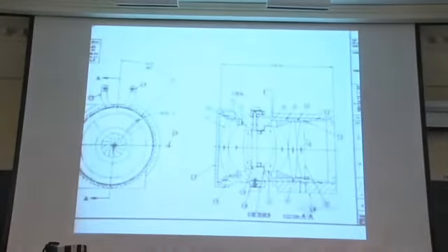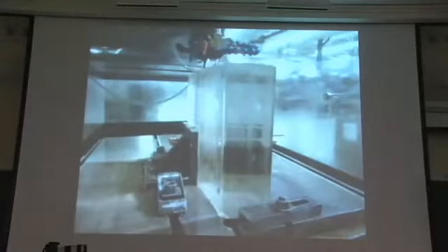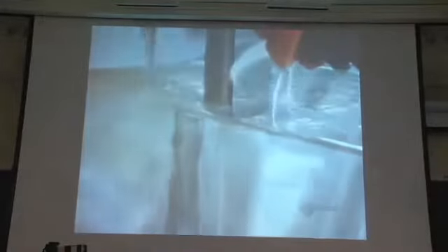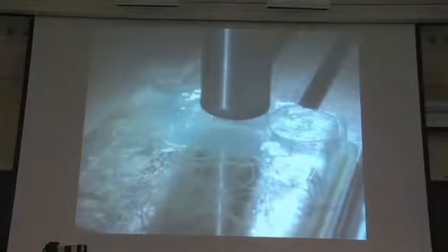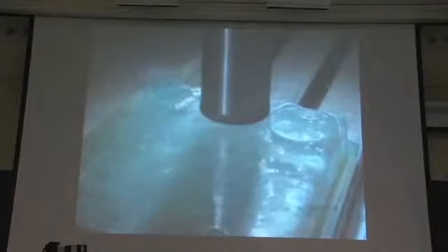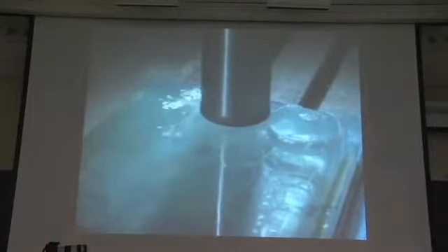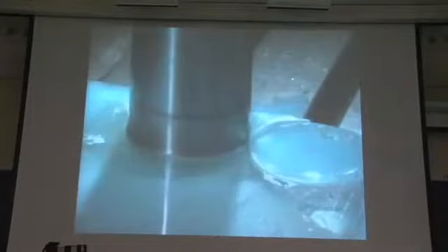These television lenses start with a very precise design. A diamond blade slices up a block of specially selected optical glass, while coolant prevents the blade from burning it. The slices then go under a diamond drill, which cuts several puck-sized discs from one glass slice. The operator is careful to keep waste to a minimum.